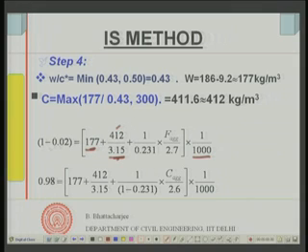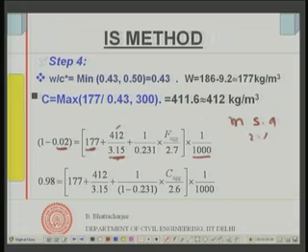So, in 1 meter cube, this will be the volume fraction of air, because we said there will be 2% air corresponding to our MSA 20. MSA 20 corresponds to 2% air content, and therefore, this 2% I am subtracting from 1 meter cube.